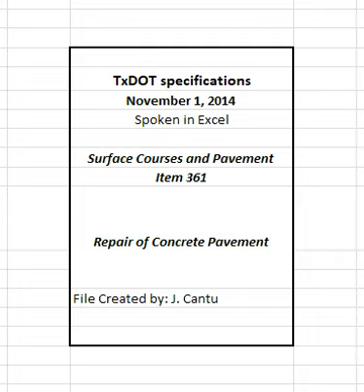Match the grade and alignment of existing concrete pavement. Replace any asphalt overlay and shoulder material removed with new asphalt concrete material after concrete strength requirements have been met. Remove repair area debris from the right-of-way each day. Concrete pavement may be open to traffic when specified strength is achieved.